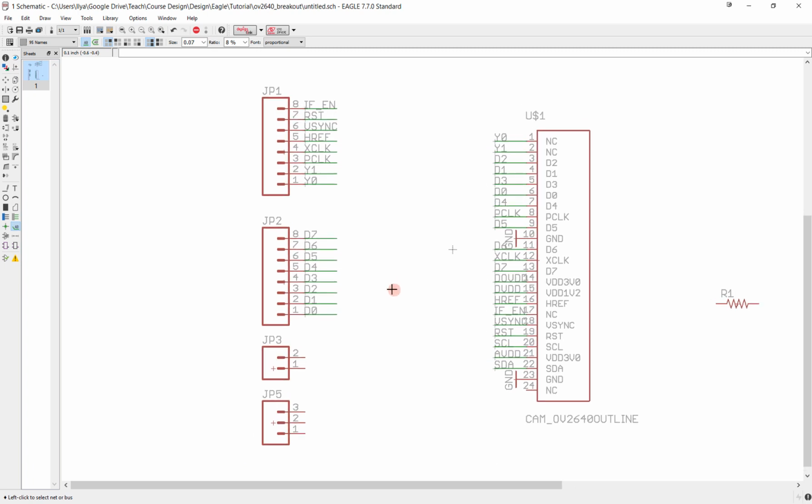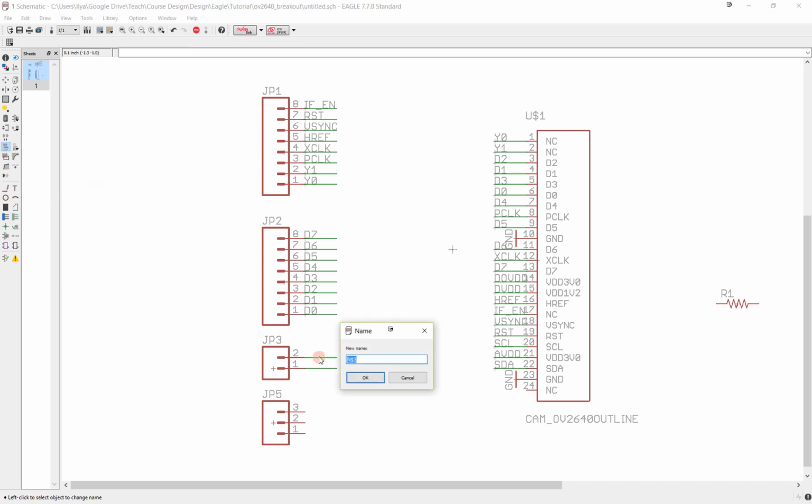So now a couple more things just to make this a bit nicer, and that's for the interface. I want to also have breakouts for the SDA and the SCL with pull-ups. And so here, let me again make this the same kind of way. A separate header here. And so these I'm going to call SDA and SCL.